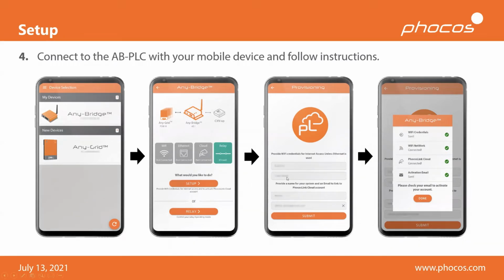When you first open the app, you scan for BLE devices. You'll find the Bridge ABPLC. If in this case you're using a PSWH inverter, you will also see the inverter because the inverter also has BLE connectivity. In this case, you select the Bridge, and then you will be greeted with this screen. The fact that the relay is green and closed here already indicates that you've successfully connected to the Bridge ABPLC because it's the default setting for the relay. I'll mention what that relay does a little bit later in the session.